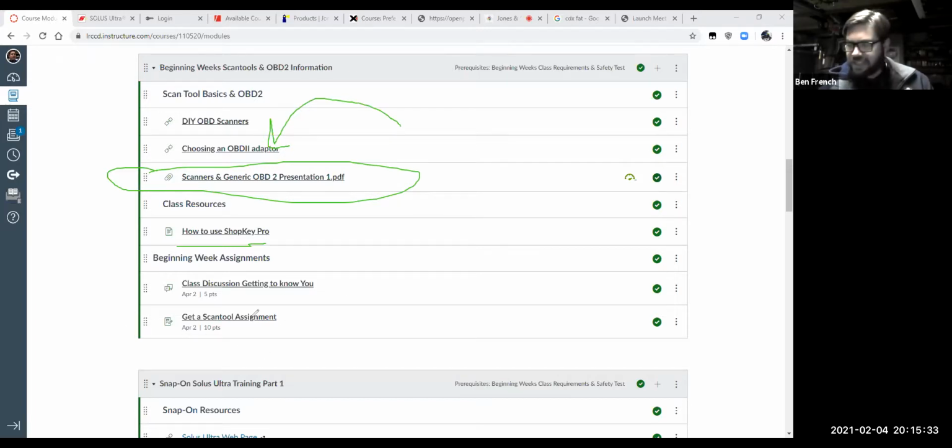If you get a scanner and get going, you're not going to hurt anything by getting in your driveway and turning your key on, engine off, plugging in your scan tool, and trying to pull some information. Try to go through the different test modes. Pull mode 1 data, pull codes, pull data, and see what you can see, and just kind of hunt around. Okay. You can also,